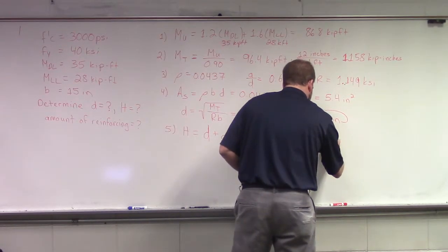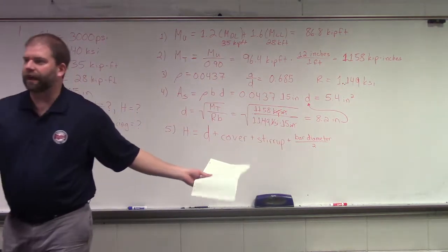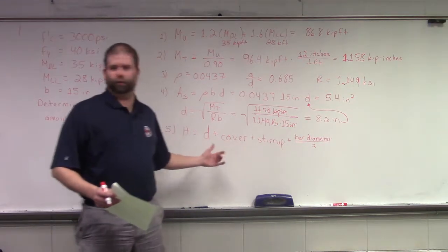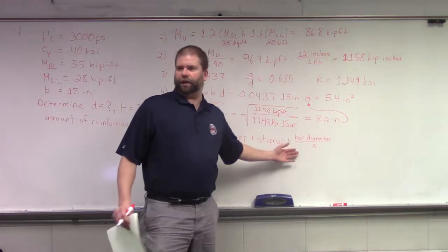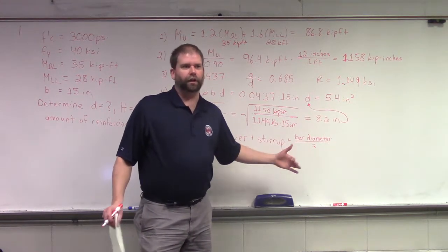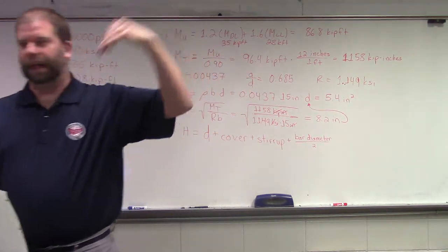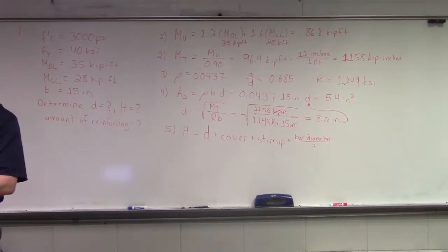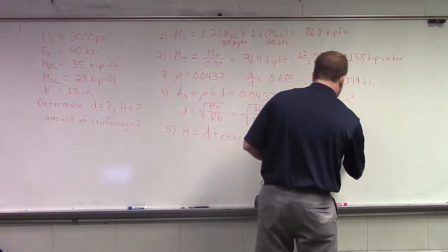I forgot. Typically speaking, because of the size of steel that we're working with, and we'll get to it in a second when we calculate our final number, we should typically be fine just using 1 inch diameter for your bar, okay? If we end up bumping ourselves up to number 10 steel where we've got that extra 1/4 of an inch of distance, we're probably fudging for that in our depth factor when we're rounding up, okay? Skip all this and say 1 inch steel.